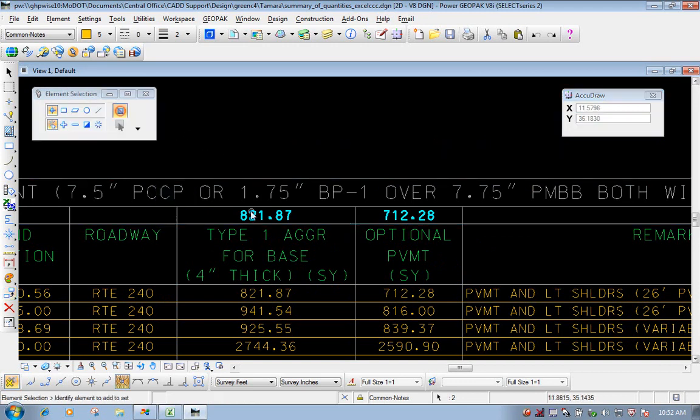And you'll still see that you have two items selected out there. To drop off that selection set, I can just left click out on the screen somewhere, making sure that in the element selection tool, I have it set to individual and new. If I just left click out on the screen somewhere, it drops off that selection set, so you don't have anything selected now.